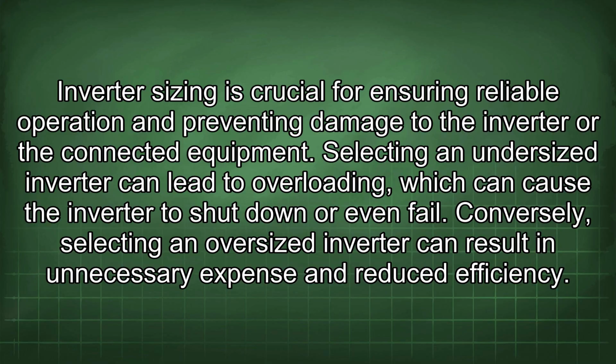Inverter sizing is crucial for ensuring reliable operation and preventing damage to the inverter or the connected equipment. Selecting an undersized inverter can lead to overloading, which can cause the inverter to shut down or even fail. Conversely, selecting an oversized inverter can result in unnecessary expense and reduced efficiency.